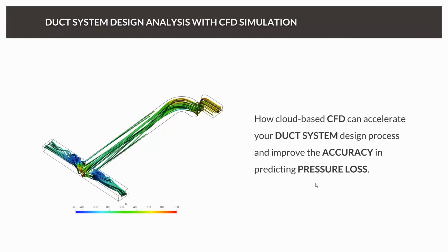And one very, I think, famous, or let's say important procedure for this is the K loss factor method. And I know there are a lot of different systems. What they all have in common is that they are actually calculating the performance of the total system by treating the flow as a simplified Bernoulli flow, so a simplified pipe flow. And you have different loss factors for the segments, and then you can calculate the overall loss factor based on the single factors.